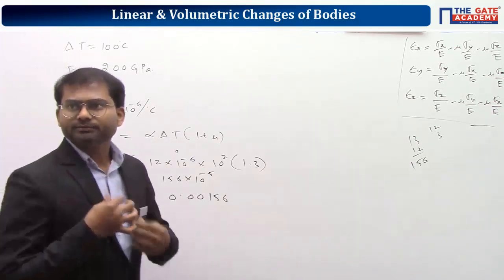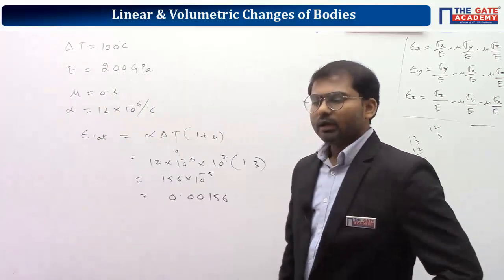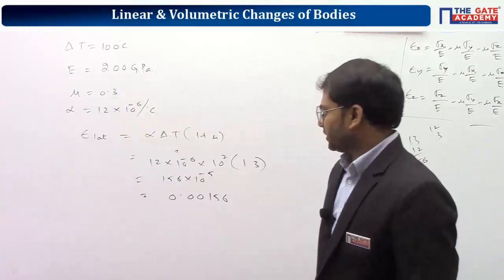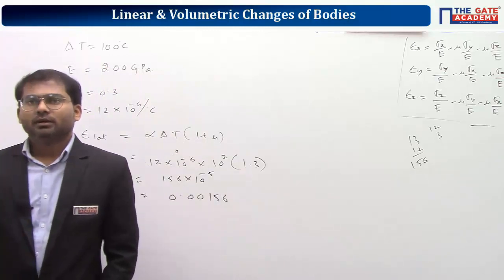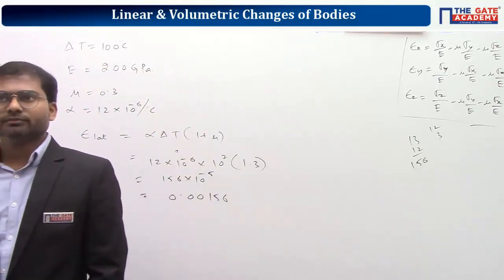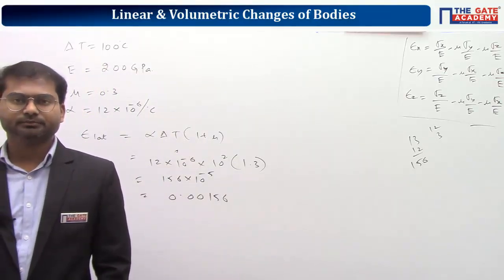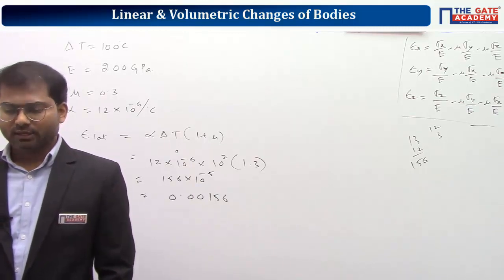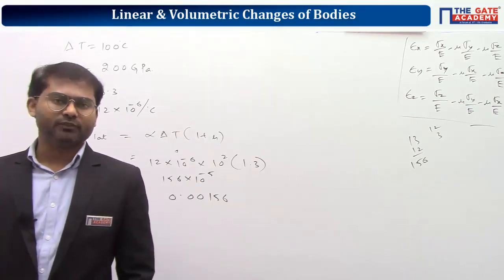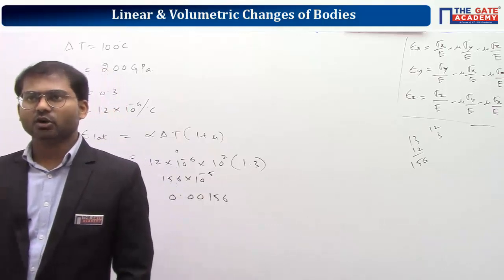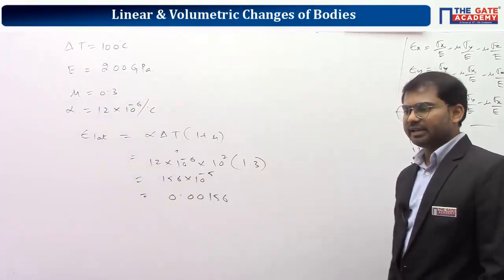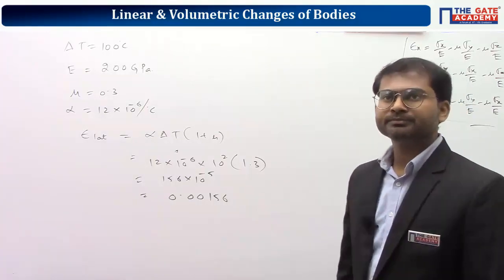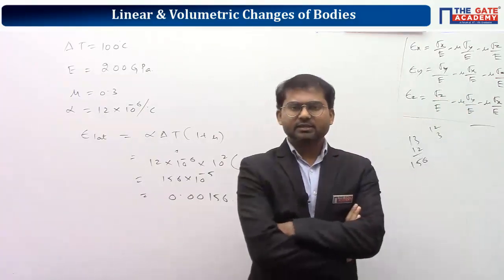So tell me, we are coming to the summary here. Brittle materials undergo plastic deformation, yes or no? We're looking at the summary of this chapter, the first chapter. The answer is no. Very good. Brittle materials cannot undergo plastic deformation. Only ductile materials can undergo plastic deformation. Ultimate stress is the stress the material can take up to failure. Is it true or false? The answer is false.